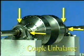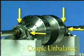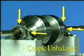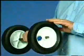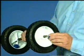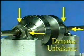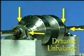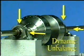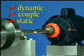So for a couple unbalance, the vertical to vertical readings or the horizontal to horizontal readings would be 180 degrees out of phase. Any combination of static and couple unbalance is referred to as dynamic unbalance. The phase change from vertical to vertical or horizontal to horizontal could be any combination depending on the amount and location of the unbalance.